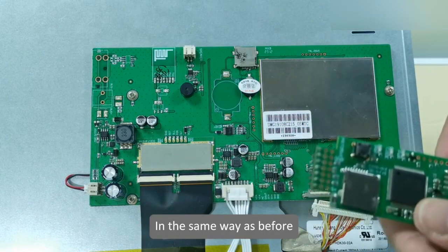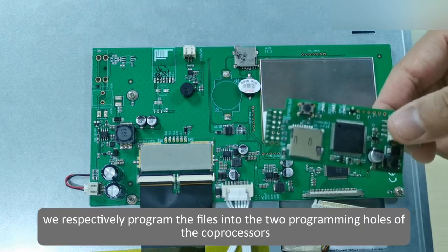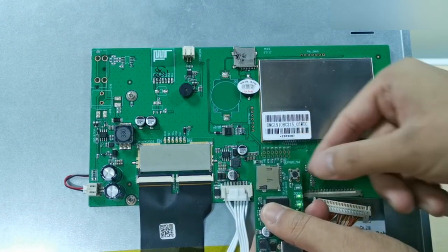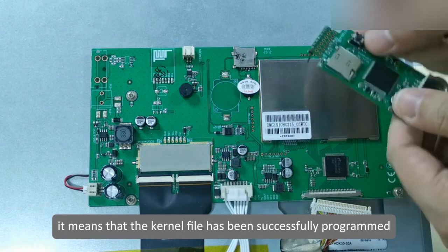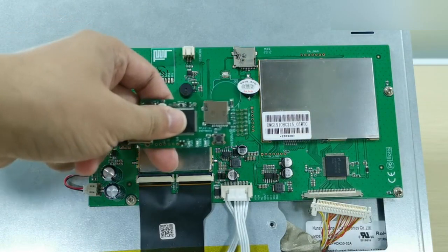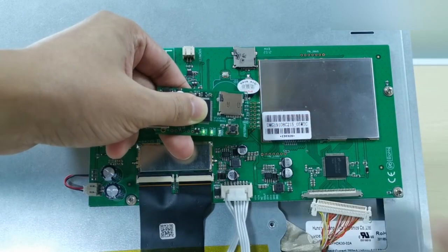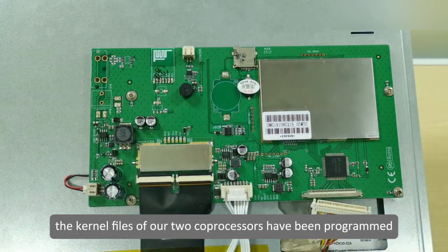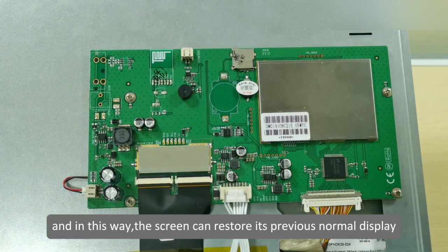In the same way as before, we respectively program the files into the two programming holes of the coprocessors. When the red light turns on, it means that the kernel file has been successfully programmed. In this way, the kernel files of our two coprocessors have been programmed. Finally, we connect the LCD cable properly, and in this way, the screen can restore its previous normal display.